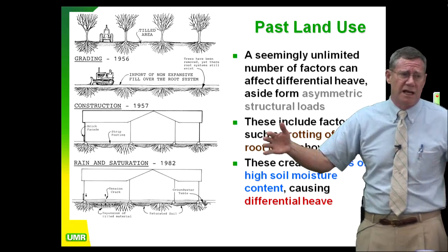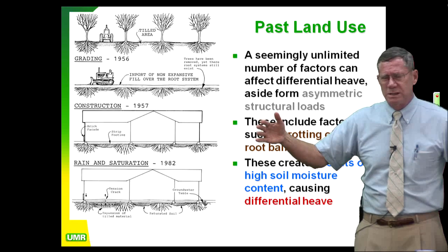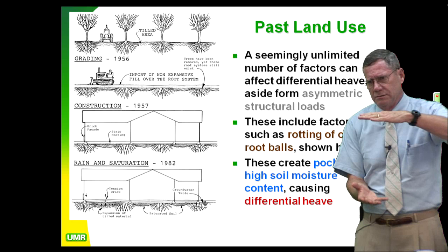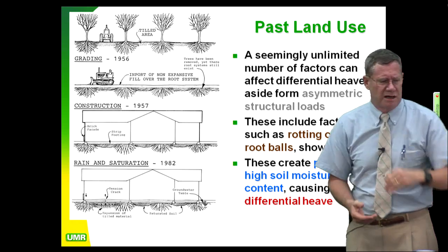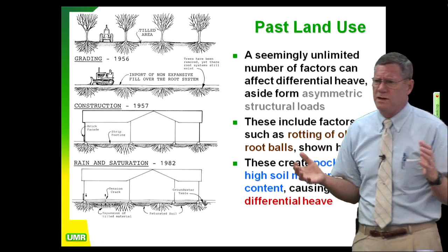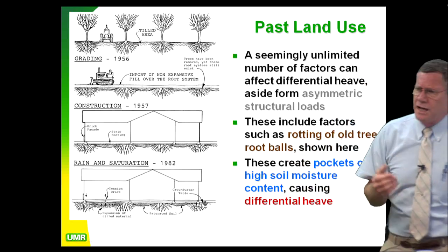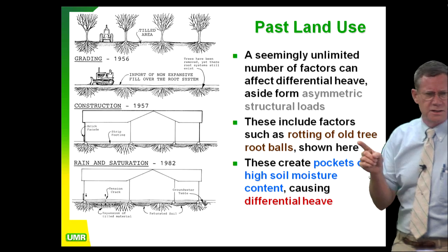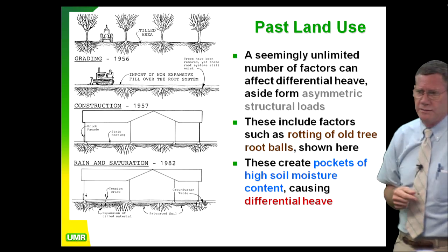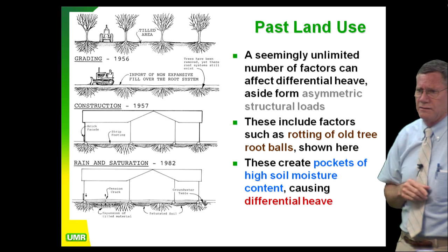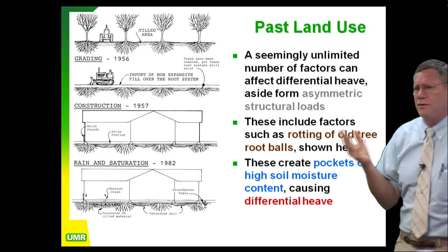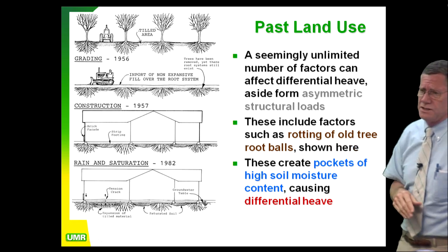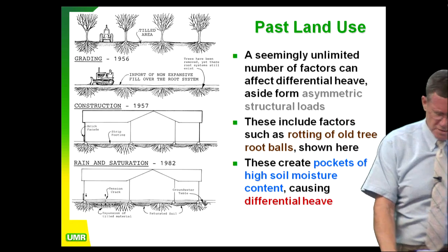So the only way you putz around on expansive soils with a slab is, two ways. One, pre-pond the site for 6 weeks to 4 months, and then put in a healthy, stout section, 14 inches, something like that. Something that's big and beefy and bomb-proof. Now, that seems like a lot of concrete. That's less concrete than the first letters from your attorney writing back. Attorneys don't do anything for less than about $2,500. They don't even blow their nose for less than that. So it increases the cost of the foundation some, but it makes it a much more resilient structure.